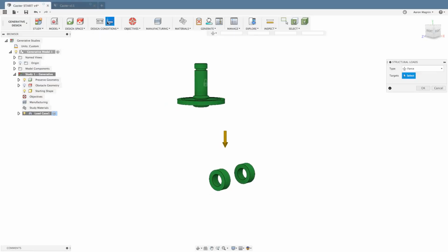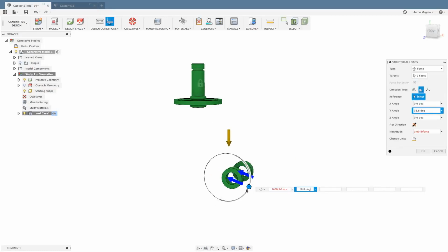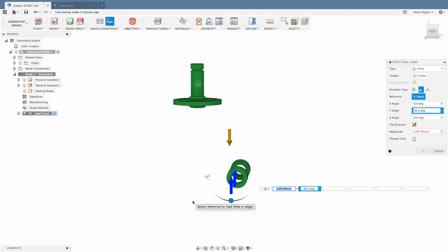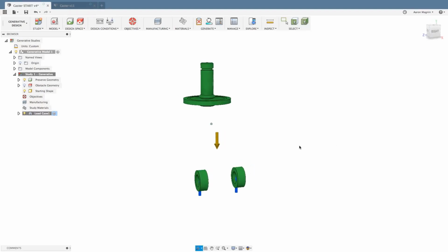Next thing I want to do is define some structural loads. So I'll select the option. I could also use L on my keyboard. And probably the biggest load is just this reaction at the bottom, if the weight is acting against this. So we'll type in a value here to use as my magnitude. And this has been improved significantly over the external piece because we can very easily change the direction. As you can see, I can use the triad handles to rotate directions in all the major directions. So very handy and nice to be able to use that. I'll type in 150 pounds. Maybe that's my design consideration, the layout that I want to use.